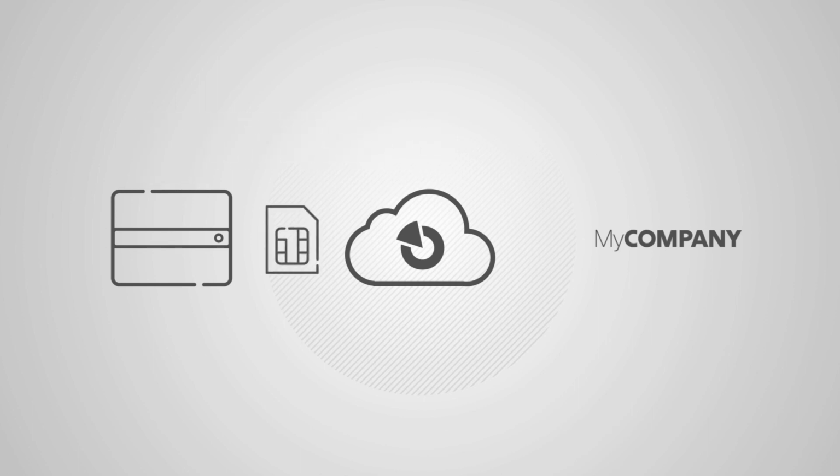If a data channel is not available, the cloud creates a configuration Super SMS and sends it to the control panel via GSM. Same as before, the control panel must not be in service mode and the USB must be unplugged. After the registration, the cloud must get the confirmation of the successful configuration from the control panel to be considered as configured. Data configuration is confirmed via the data channel. Super SMS configuration is confirmed via an SMS sent from the control panel.